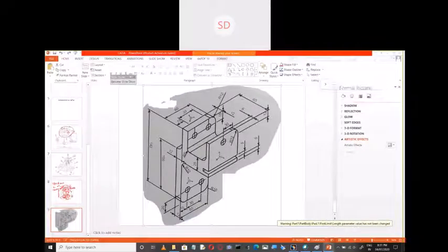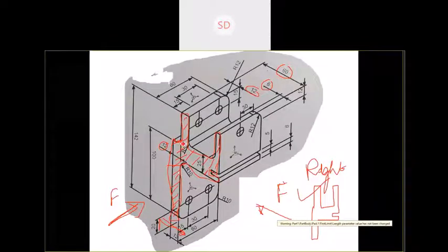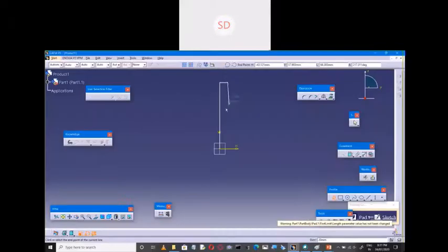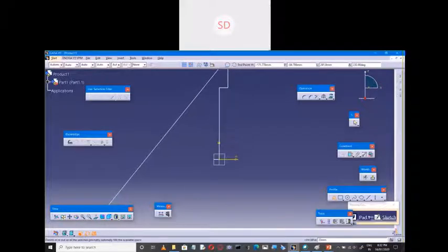Next, check up to this point what you have drawn. You have drawn 100, and 12 mm. Now 142 minus 100, this total height is 42 mm. So we will go for the length as 42, angle as 90. You can use the fit option.